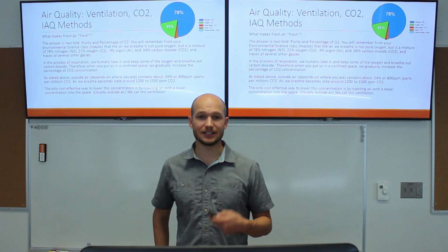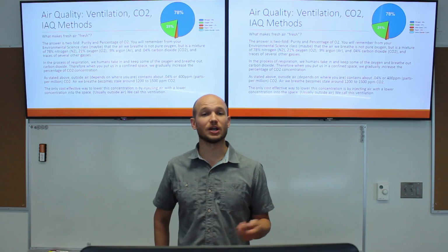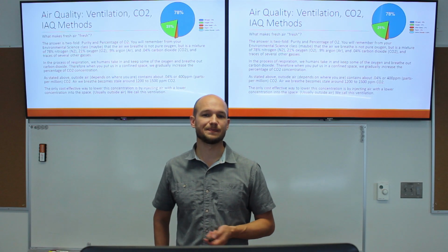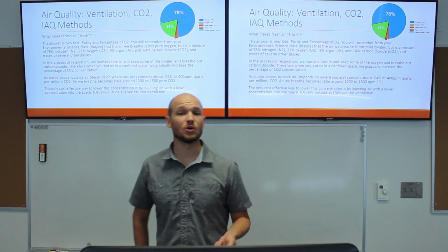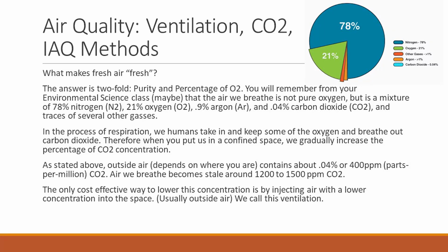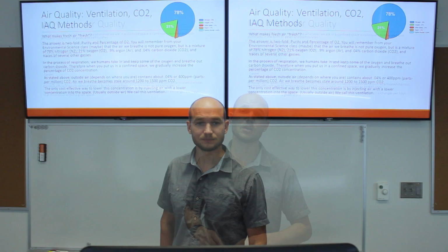Air quality, ventilation, CO2, indoor air quality methods. So again, I'm not going to dig through all this, but if you want to pause it, read through it, it's good information, it's good to know. Basically CO2, that's the air we breathe, and the higher that is, the worse it's going to be, right? It's going to be harder to breathe. The air becomes stale around 1,200 to 1,500 parts per million.